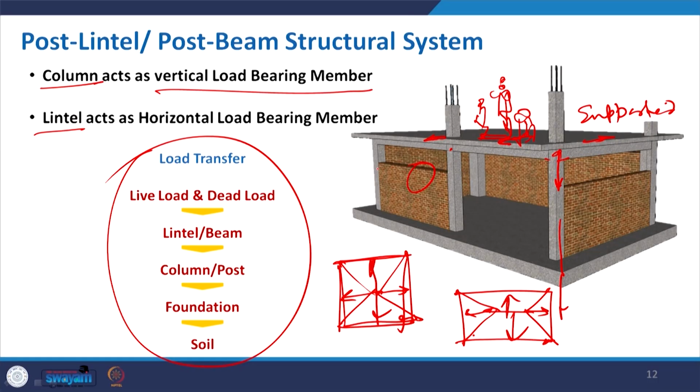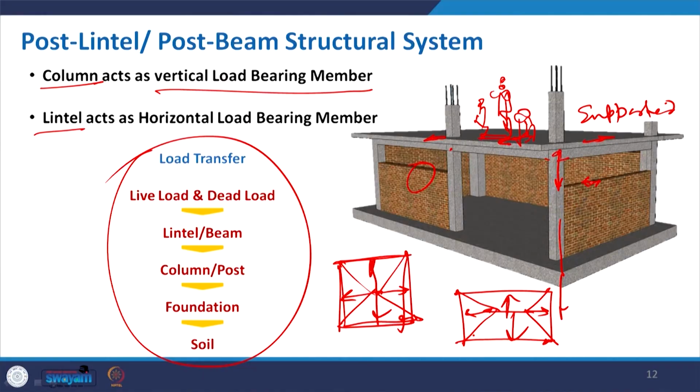So, essentially it will not act as a structural member, and that is why with this structure we can considerably reduce the thickness of the wall. Normally in earlier structures, brickwork may be 1 meter, or 3 feet, thick for old public buildings and buildings of earlier times. But now we can reduce it, even go with 125 mm thick, 5-inch or 10-inch thick brickwork for the external walls, and for internal walls we can reduce it even further.